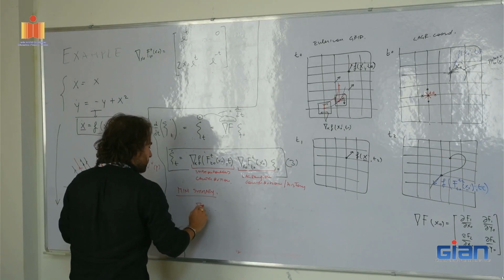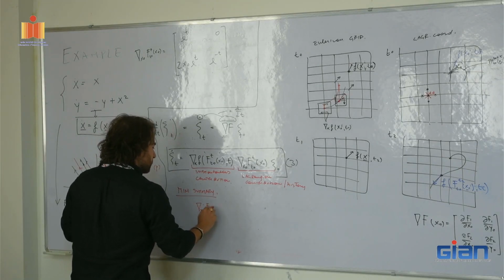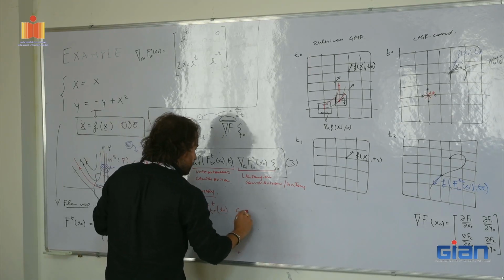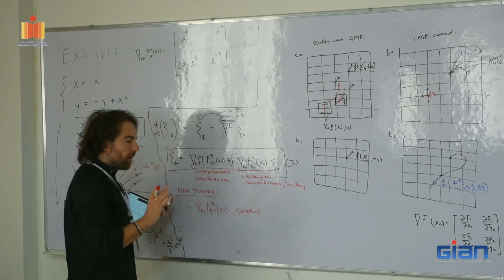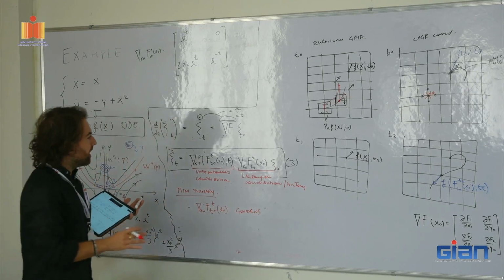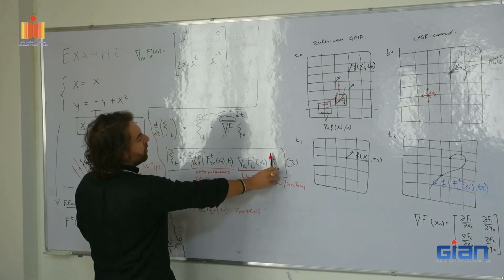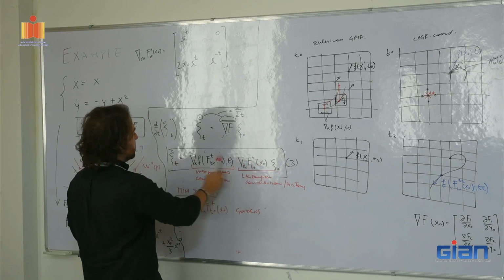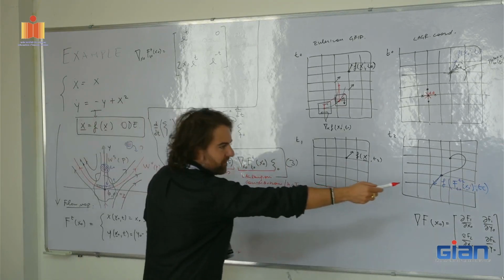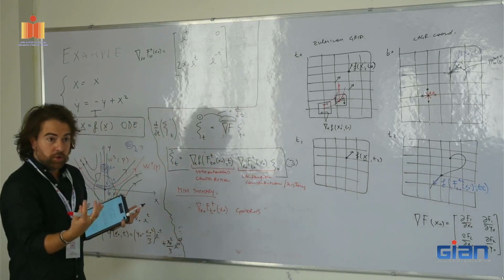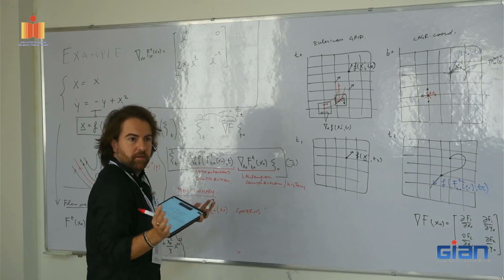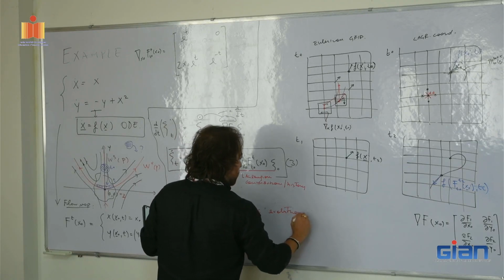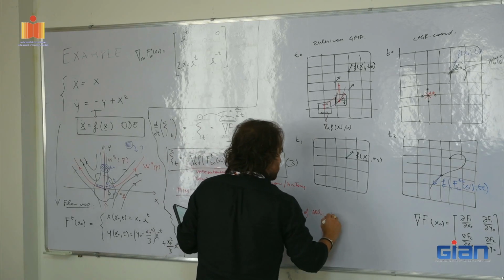dF governs the evolution of every possible fiber. This guy is really the queen, because you pick one, zeta 0, and it's going to spit out exactly the velocity of that particular perturbation at some time t, the final position of that particular perturbation, but all the juice is in the deformation gradient. So it governs the evolution of all material fibers.